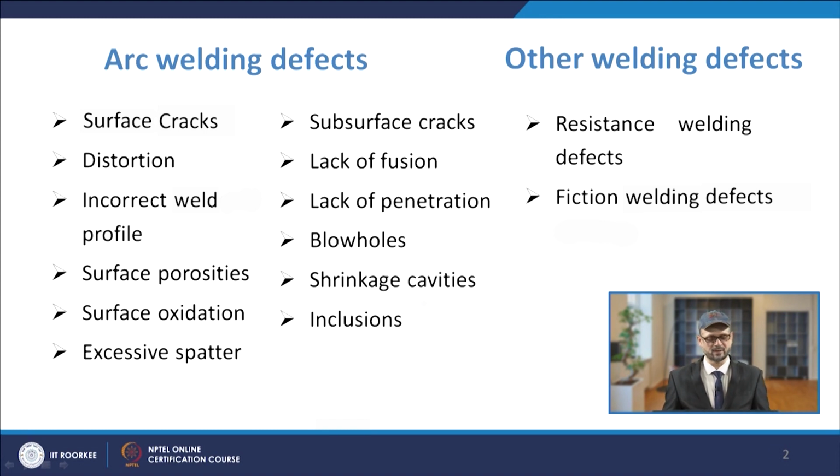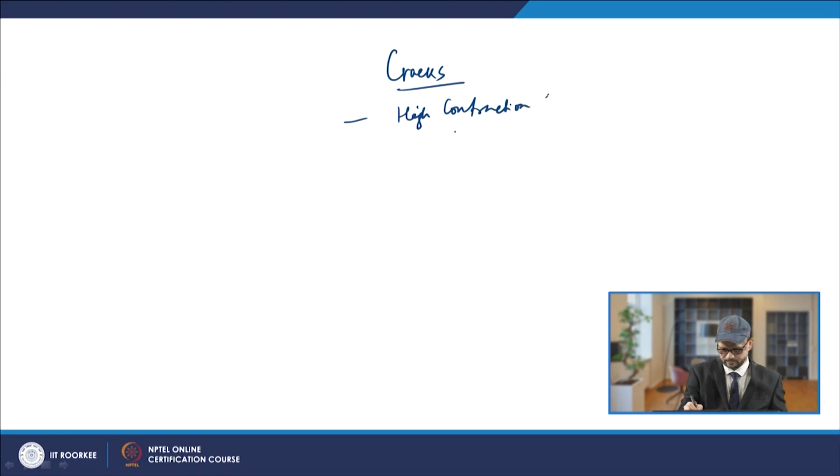So, coming to the cracks, we have studied very much about the cracks. We have already studied that there are many reasons, and this is because of high contraction stresses. When these stresses become more than the strength of the metal at that particular high temperature, the crack results.